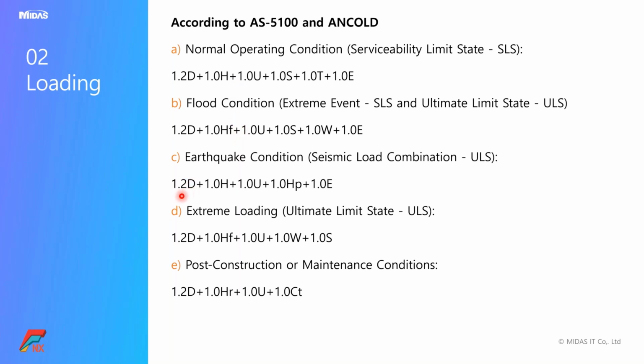But in Indian codes, it was the factor of safety that changed for different load combinations against sliding and so on. So this is a very basic difference. And now in this model, we have considered load combination E according to the Indian standard.